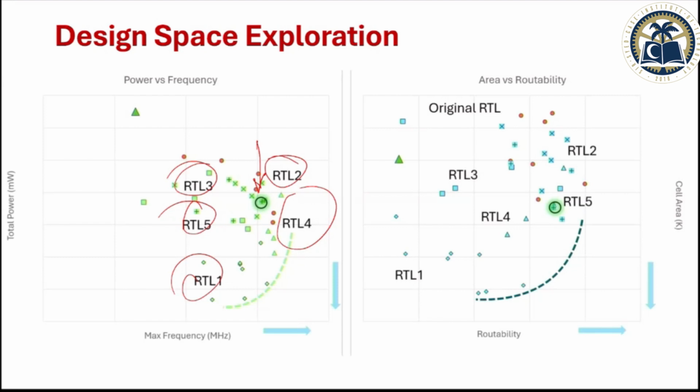So under all these design constraints, you have to fit yourself at the best place. And that best place is not very easy to figure out, because once you find out where you actually sit in this design space, you are away from RTL. There is an RTL design, then you have to synthesize it, then you do place and route, and only then will you find out how fast you can clock your circuit. So all these generative AI tools which have agents keep taking your RTL and passing it to the layout and synthesis tools, giving you an estimate of where you stand in this trade-off, so that you find the best place where you should be.